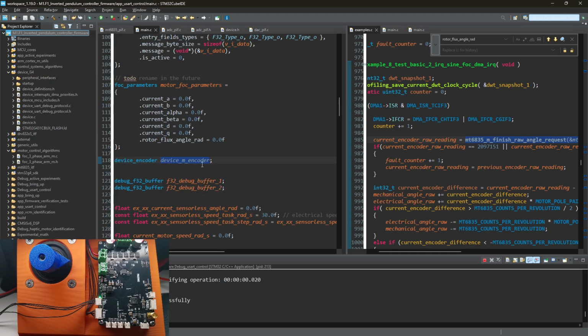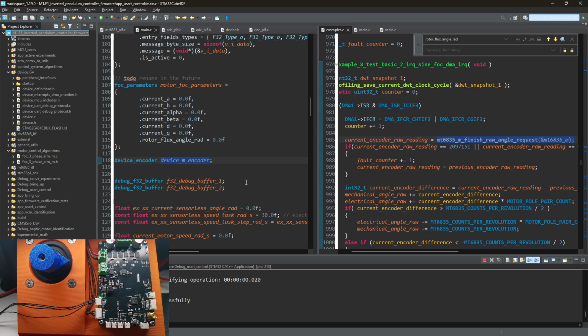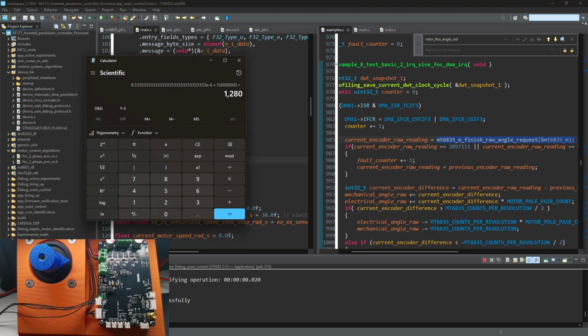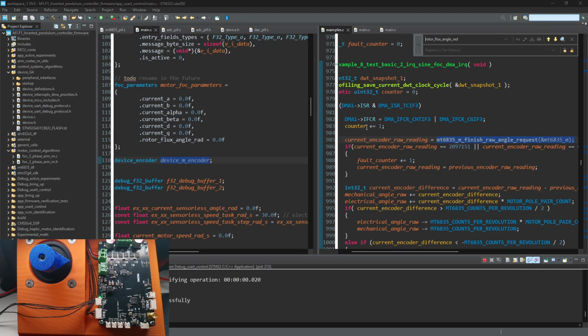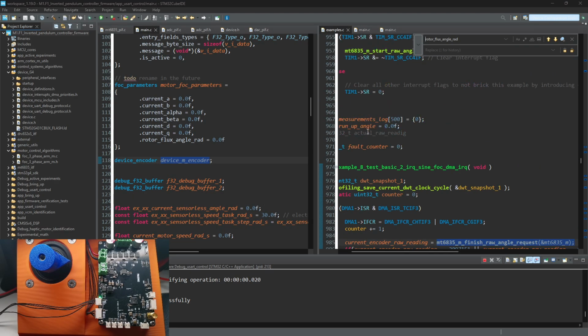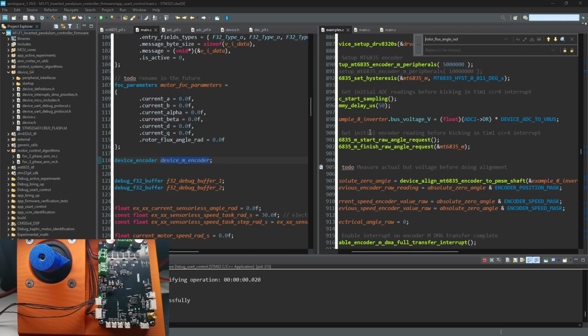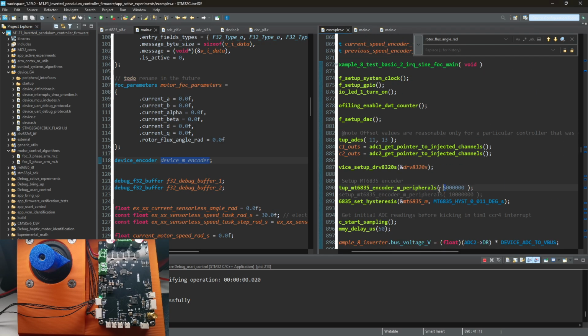Active experiments. So from our calculations, we saw that we have 4.8 megahertz and we need to request a frequency below it. So in our setup code, let's request 4, which will give us actually 2.9-ish, because the divider should be a power of 2.